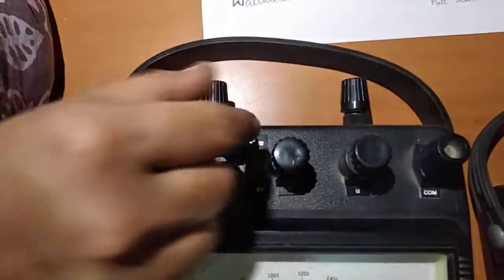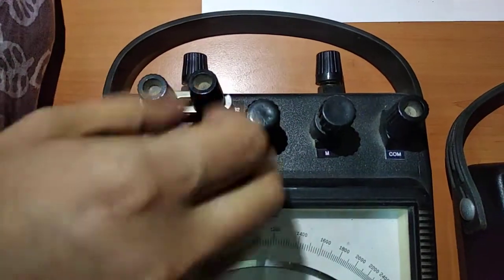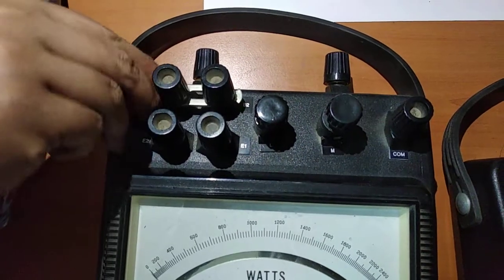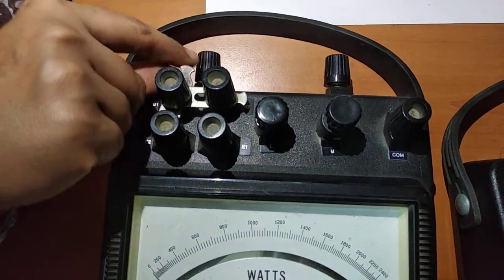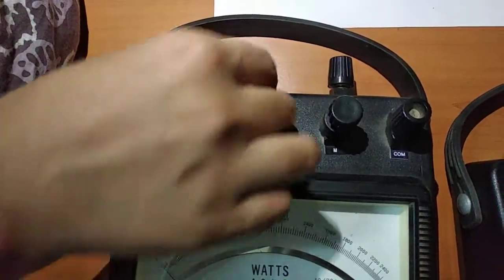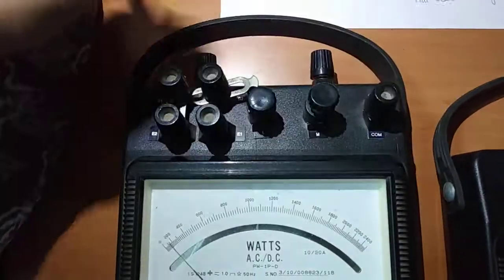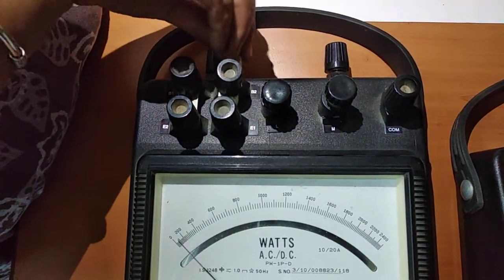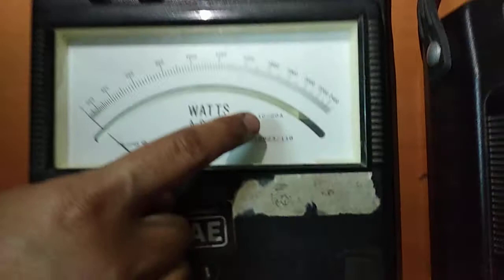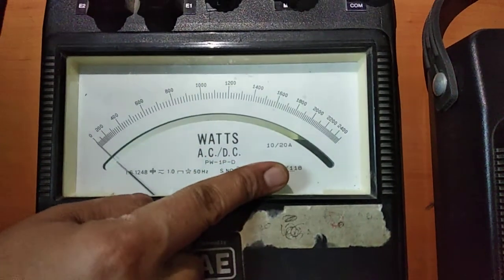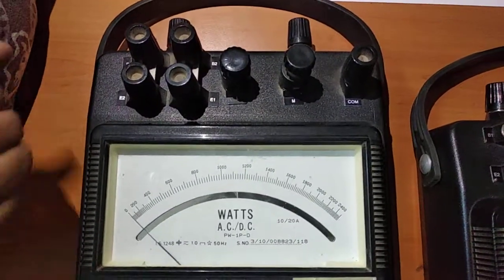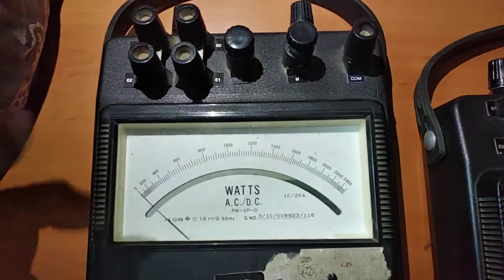And if we connect the terminals in such a way that B1 gets connected to E2 and B2 gets connected to E1, that means to say they are connected in parallel, then the wattmeter is calibrated to measure the high current range of that device. In this condition, the same wattmeter will be used to read higher current rating. Alright, but for this experiment, we'll be limiting it to the lower current range because we have the necessity only up to that.